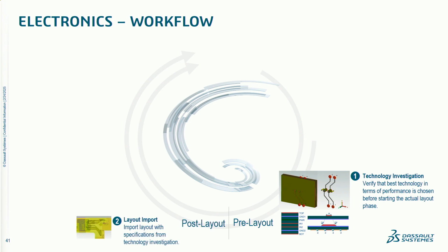And you'll see in another slide, we can import just about any ECAD file out there, any sort of EDA file that you have, if it's Cadence, Altium, Zuken, Mentor Graphics, we can bring it in directly, natively, with the full detail, every trace, every component, every via on that board. Then we can use the design checker built into CST, and this looks at some basic design rules to prevent issues for SI, PI, as well as electromagnetic compatibility challenges. And it helps do a first check on things to get rid of some bad oops mistakes right off the start.